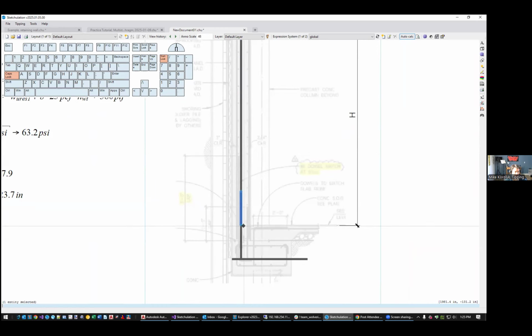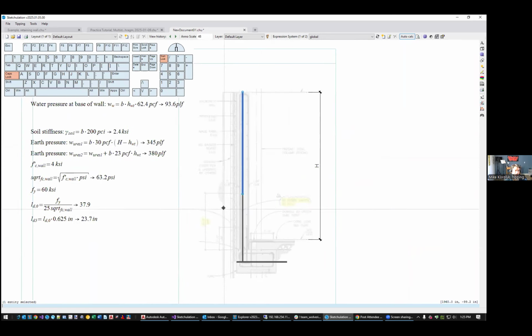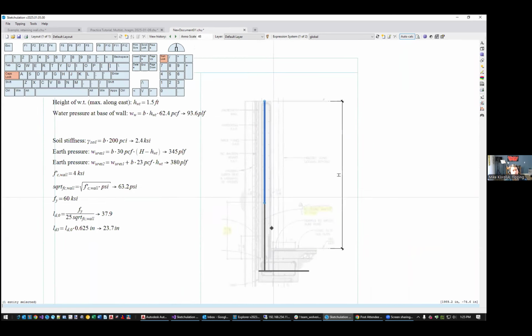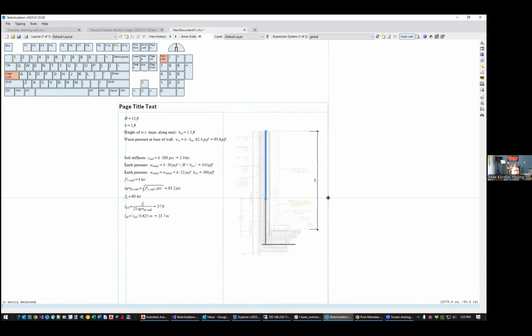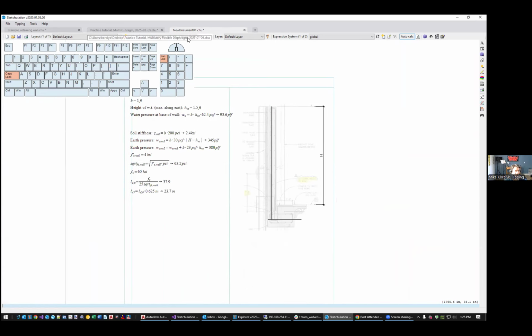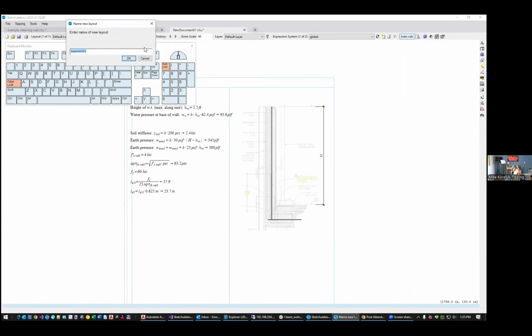We have down at the bottom fully developed number 5s at 6, and then we go up a little bit and we have partially developed, and we go up a little bit more and we have even less developed, and then we get above the 5-foot line, and we have the number 5s at 12. So those cross sections, we'll create a cross section layout. And we do this because cross sections want to be drawn at a different annotation scale than the wall.